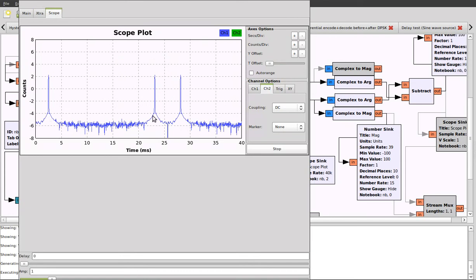And you can see, although you can't really get a sense of the frequency, you can actually just use this as a debugging technique to make sure that your transform is doing the correct thing. And once again, because we were operating on real samples to begin with, we have this symmetry about the middle frequency. So you could ignore and throw away the top half because it doesn't contain any more information. So you can see here that this is just a very simple, well, not quite simple, but convoluted manner of debugging the fast Fourier transform block itself. So you can see here that we have a peak where we expect, and everything appears to be working.